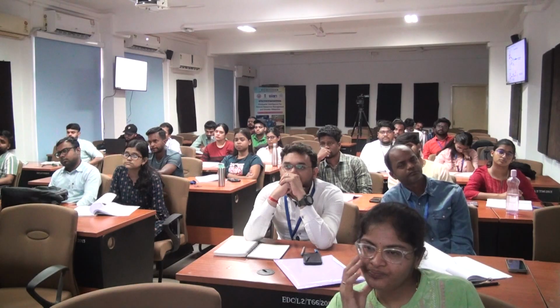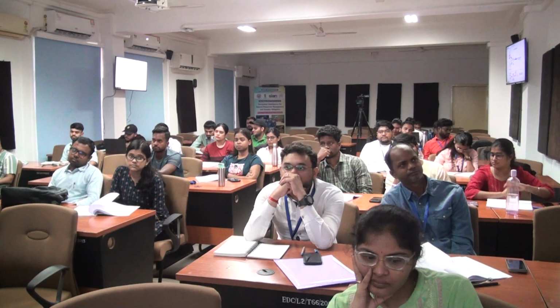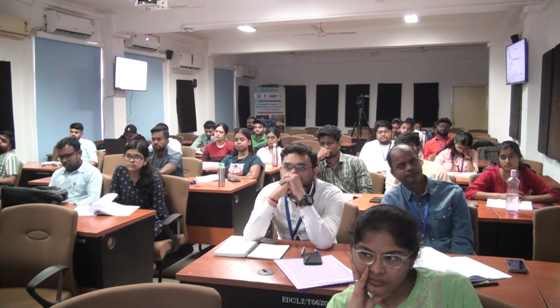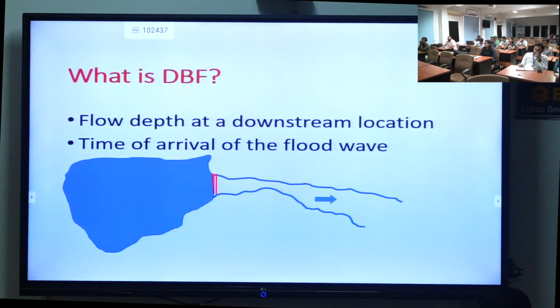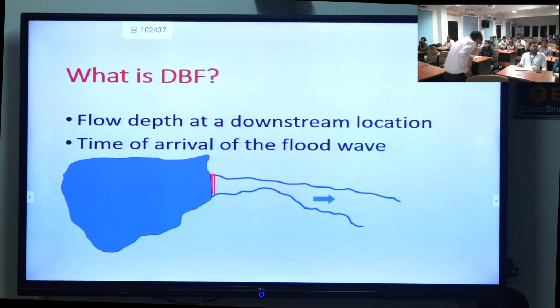The important thing for us is, if the dam breaks, then what is the flow depth or the water level at a downstream location. Maybe my city is located 40 kilometers downstream of the dam. So in my city, what is the expected highest water level due to this accident? And the second most important thing is, what is the time of travel?